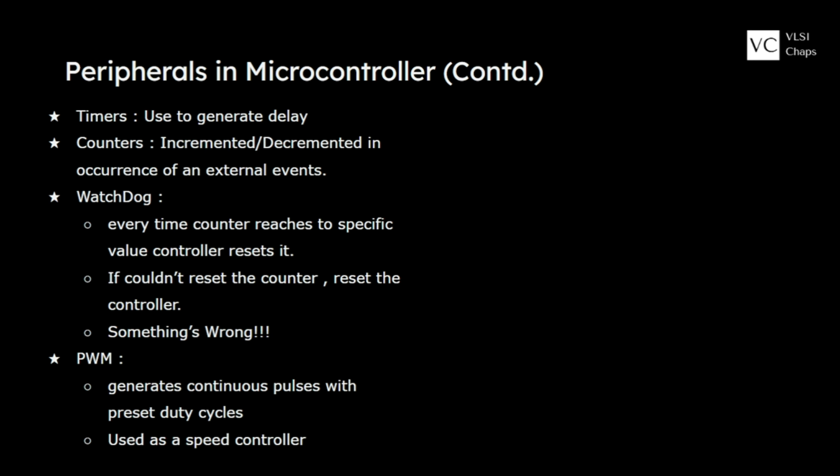So what I will do is have a particular pin which I will continuously monitor, so that once a person passes through that particular sensor, that pin will give a certain output, let's say a logic high. So I will count how many logic highs I am receiving in a certain period of time. Based on the number of logic highs I get, I will increment a particular counter or register, and based on that I will be able to identify that this number of persons have passed through that particular gateway.